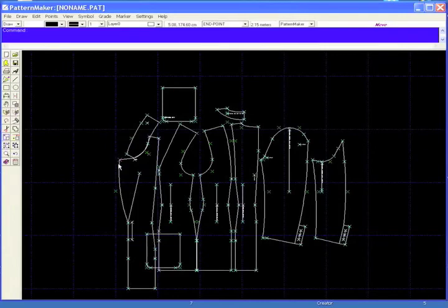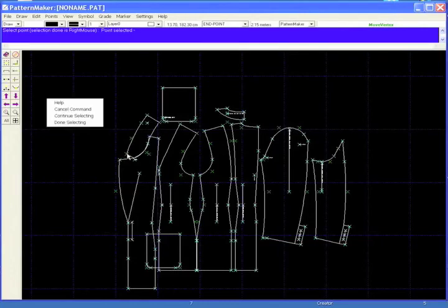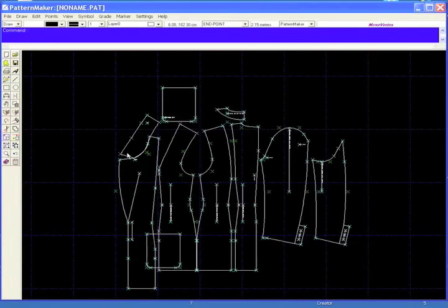And now you see that this is wider than this. If I want this also wider, I can move this point also. I move this point, and I'm done selecting, and I type in R -3, 0, enter. And now you see they are equally long.